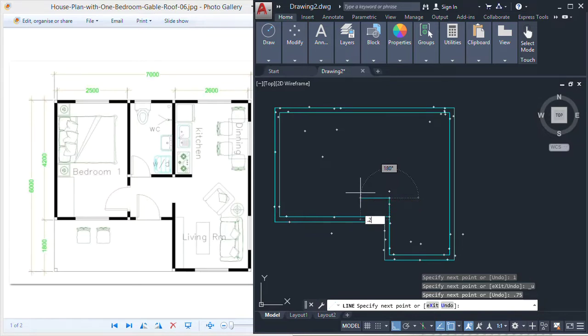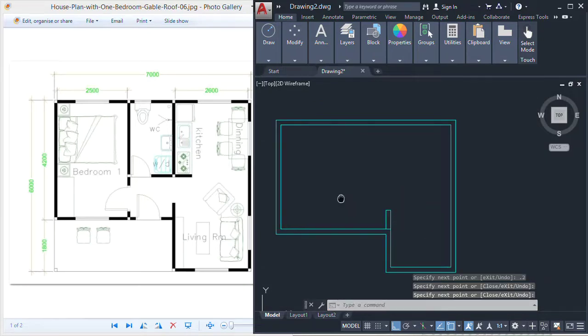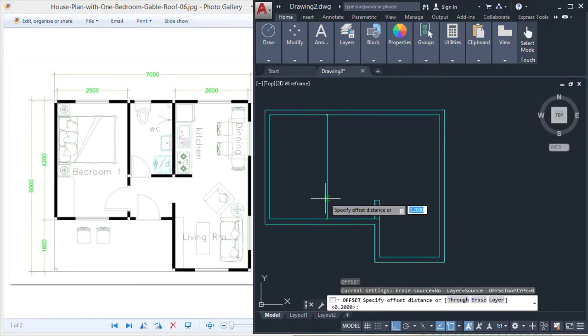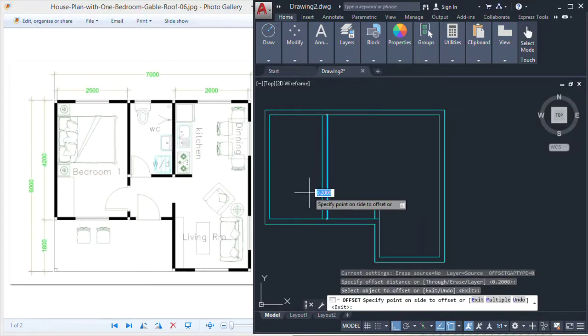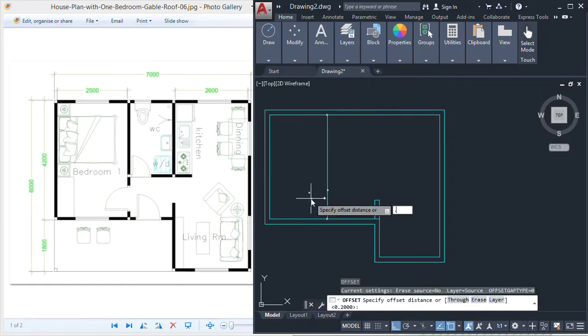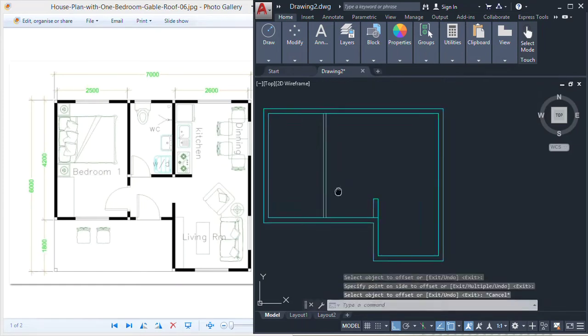So another 20. And as you can see, I didn't finish the order, so I could complete this wall and then I will put the space in it. And another wall we have here, so I'm gonna do this. I'm gonna look for the point which my line ended and just pull it till the end. I'm gonna offset it for another 20 centimeters inside, and let me take it for 10 because I know the interior wall is gonna be 10.